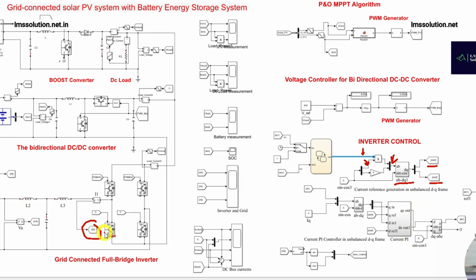Next we are going to measure the current. Here we measure the actual current of the inverter, the output current of the inverter. That is known as the A quantity, and since this is single phase, the remaining will be considered as 0. Then we convert that AB quantity into alpha beta quantity. Now we are getting the actual alpha and beta quantities, and here we have the reference.